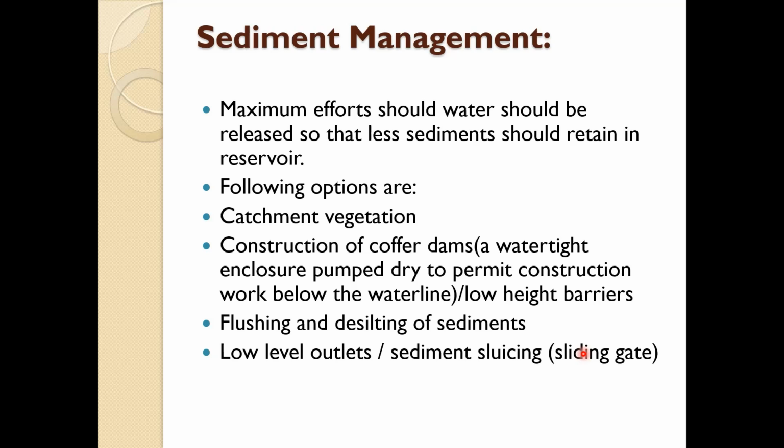Therefore, the life of the reservoir can be prolonged by constructing the dam in stages. In other words, first of all, the dam should be built lower and raised subsequently when some of its capacity gets silted. We have so many examples. Almatti Dam has been raised. Again, Koyna Dam also has been raised because we actually need more capacity. So these things can be done.